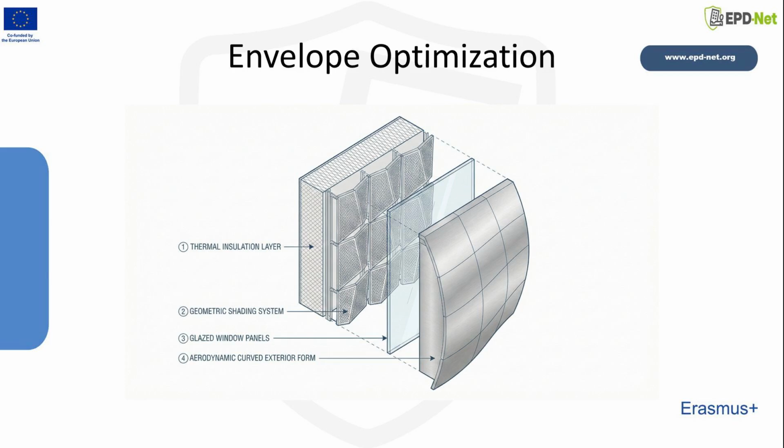Glazing and openings. The parametric model allows for the optimization of the window-to-wall ratio, WWR, size, and dimensions of windows. The objective is to strike a balance that provides sufficient daylighting while maintaining good thermal performance and avoiding excessive solar heat gain.